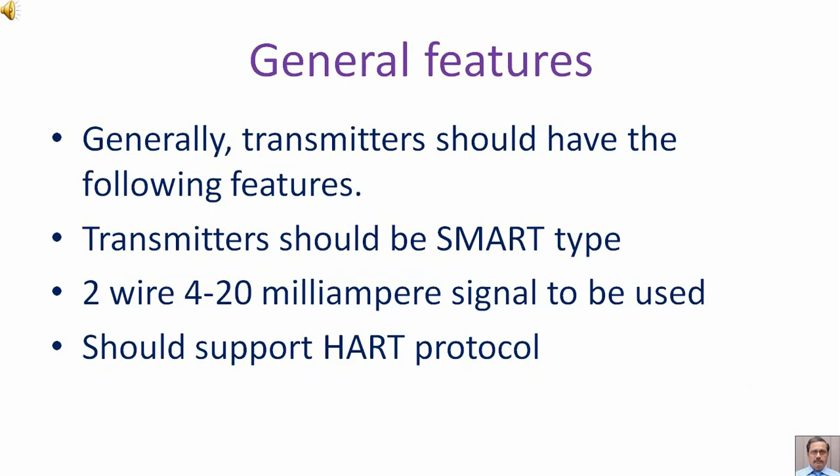General features. Generally, transmitters should have the following features. Transmitters should be smart type, 2-wire 4 to 20 milliampere signal to be used, should support HART protocol.